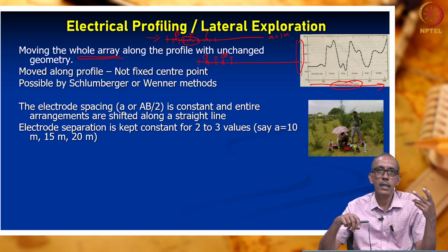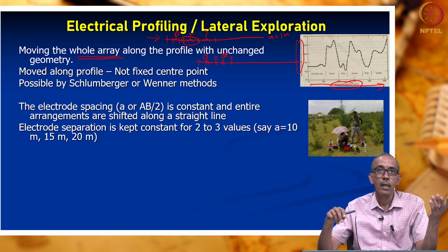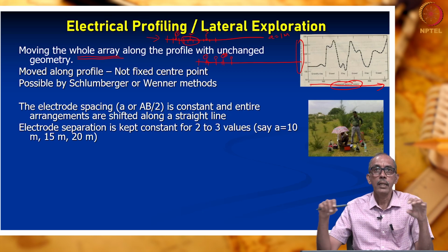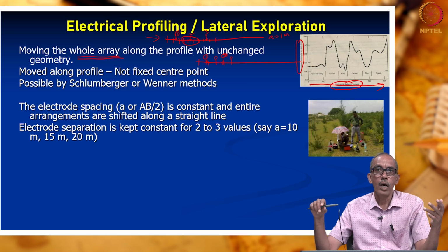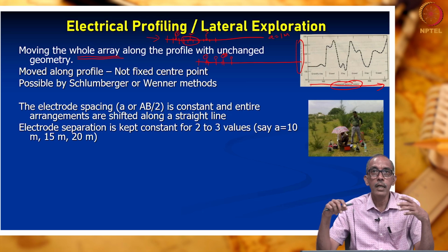For example, you are interested in laying a road. For construction of a road, if the terrain is nice, that means there is not much clay, then 1 meter of investigation may be sufficient. On the other hand, you are interested in understanding the lithology for burying a pipeline, maybe to transport water or even oil or some other fluid or gas, a large pipe which is going to be laid, let us say at a depth of 3 meters.